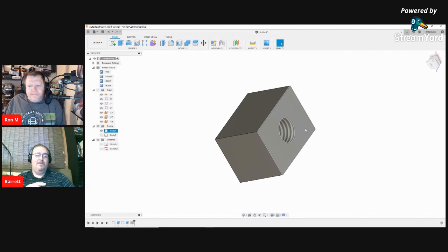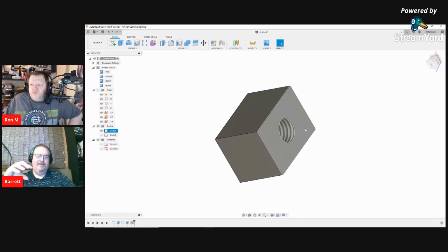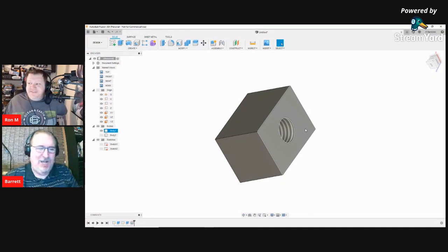Because this is a visual representation. This is intended more along the lines of, if I'm going to CAD this, okay, I'm going to tap this a certain size, it'll draw it in and show it to you. Part of the reason we do this is that a visual representation is a lot lighter on the CAD model. Imagine the helix being created for every single hole, and all of the little points and triangles necessary to model that, and then put 300 screws into an object that you're making and try to rotate your model. Okay. Yeah, it sounds a little bit much.